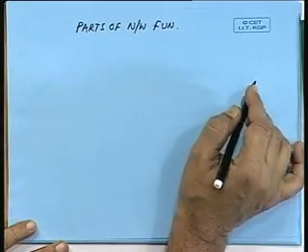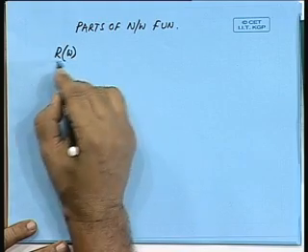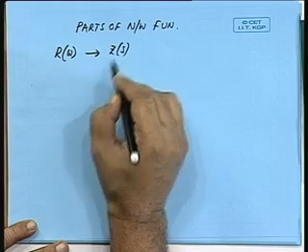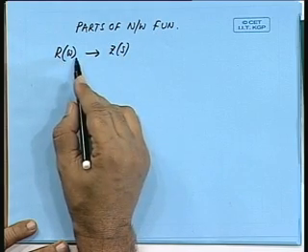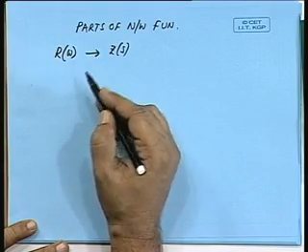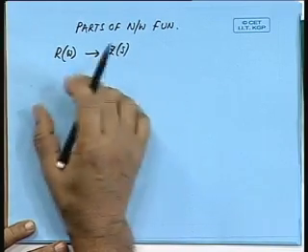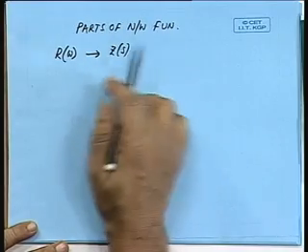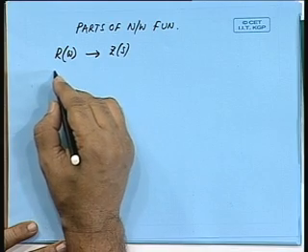Yesterday we discussed functions, R omega being given, how to get Z(S). We resolved this by substituting omega squared equal to minus S squared. We took the roots in the left half plane and finally found out the coefficients of the numerator, A0, A1 and so on.